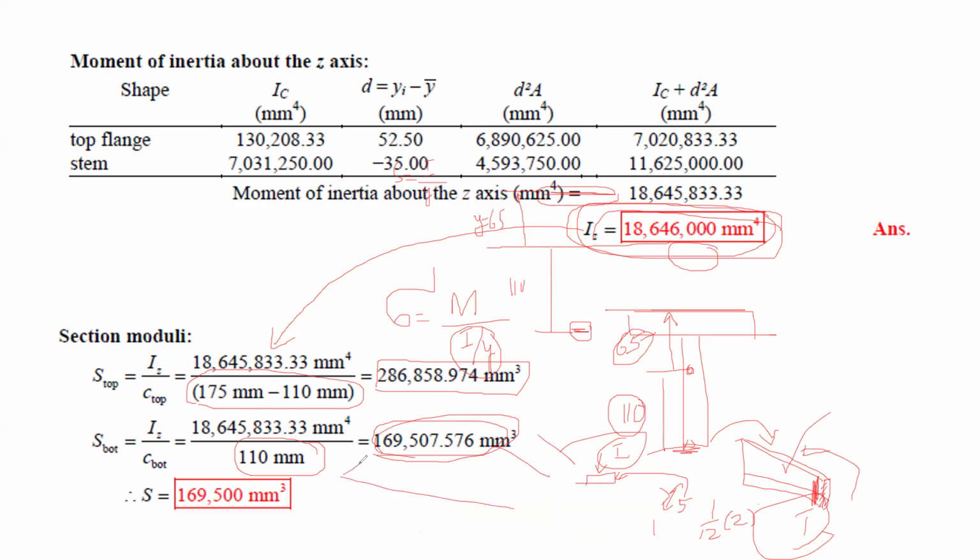So if there is a steel ruler like this, one possibility is you consider this side, this thickness, where this is B and this is height. And the other possibility is this vertical configuration, where this small dimension is B and the height is the vertical bigger side. So when you take cube, definitely the H value here is more, so it will give you the higher number, right? Maybe if you try to do the calculations, you will see it is around 3 to 4 times higher than this first configuration. That's why this configuration is weak. When you try to apply a moment like this, it will bend. But when you try to put a moment on this configuration, it will be difficult.